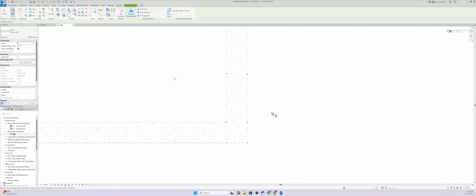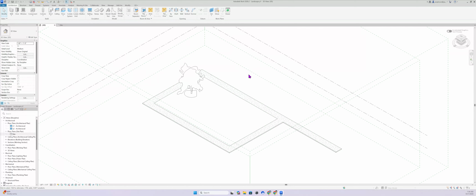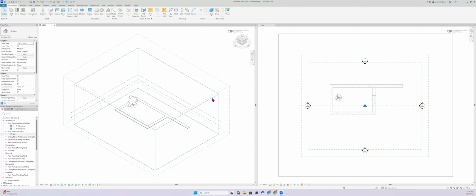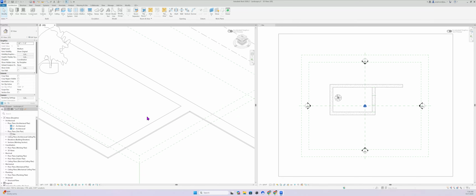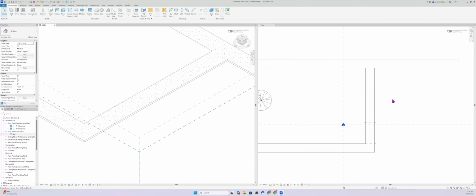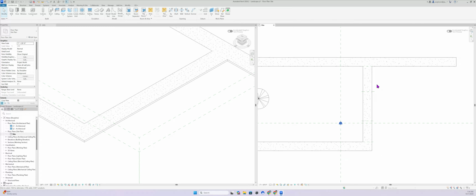Now here is the nice thing. I'm gonna choose the 3D. I'm gonna use the window tile, right? I'm gonna type WT to split those two. I'm gonna type ZA to center both things there, right? Okay, those little two shortcuts. Now let's keep a quick eye on your left side and let's modify those points. Okay, let's modify those points.